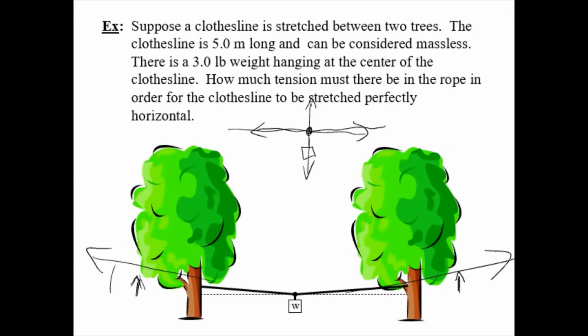The smaller you make this angle here, the bigger the tension you would need, the longer these tension vectors would have to become in order to offset the weight downward of the block. All right. So in other words, if you draw this to scale, if these ropes had bigger angles, then let's suppose the weight vector is that big. Then we just need each of these vectors to be half as long, so that when I add this amount to this amount, I end up with this amount, right?